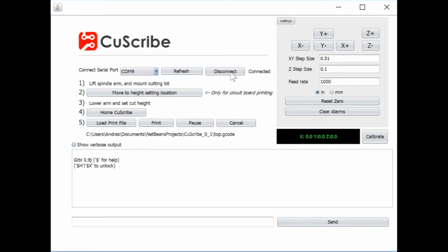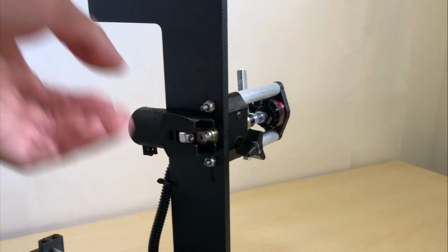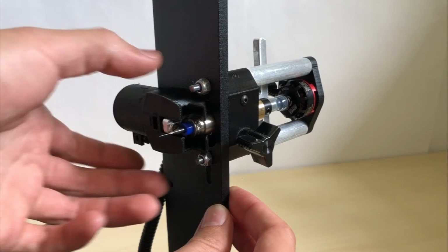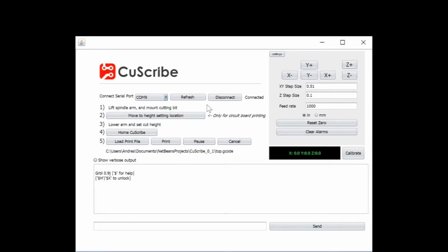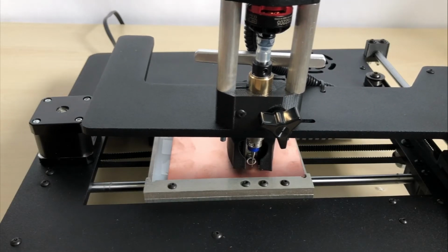Each print requires setting up the correct cutting tool, the desired cut depth, and homing the machine prior to starting the print. We secure our 0.02 inch cutting bit by loosening the height control bar and tightening the drill bit set screw as shown. Now we will set the proper cut depth. After lowering the bar, we click the Move to Height Setting Location button, which will move the machine to the center of the cutting surface.